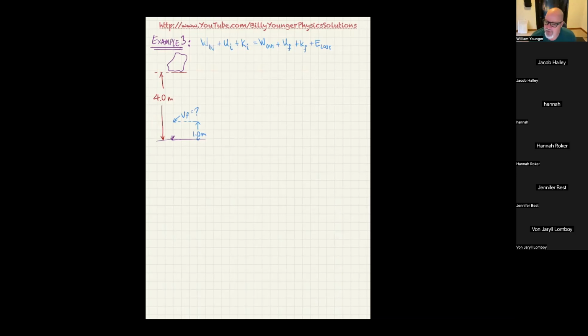So I'm picturing that as someone adding energy to the system by doing work on the system. So I just called it work in, meaning work you're putting in. But to be honest with you, anything that you deem to be a way to put energy into the system, you should put on this left-hand side where it says work in. That means work in could have 4, 5, 6, 7, 8, 9, 10, could have 20, could have any number of work in terms.